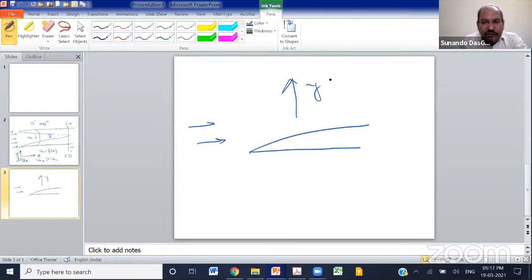So the viscous forces essentially act in a direction to reduce the inertia, to bring the fluid back to rest. But for an unbounded case, this resistance is so small that we can safely assume the flow will continue for a very long time before viscosity brings it to rest.